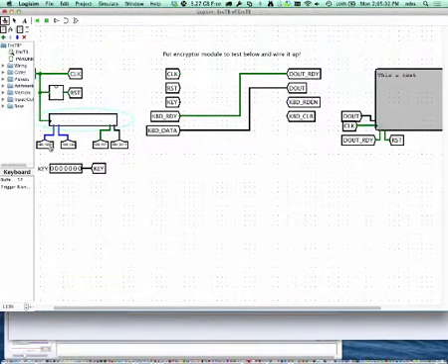And then there's also a keyboard clear. Since the keyboard presents the character only for a clock cycle, your encryptor is likely going to be slower. So you're probably going to have to manipulate this keyboard enable so that the character stays out there until you have processed it, then you let it go.